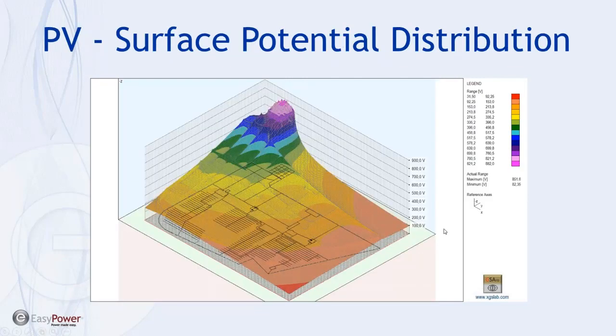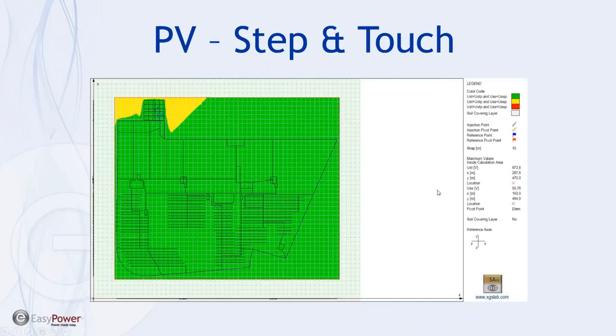What that looks like on our elevation chart now is essentially showing the same thing as the last one, but in an easier visual way to look at. You can see that the substation grid has been raised up to a very high level, and everything else that's still connected has been raised up, but not to that same extent. And then finally, the end result for this one, and I believe this is on native soil as well, we show that with that fault, with this grid design as modeled, we're all green, which means all of the step and touch hazards have been handled.